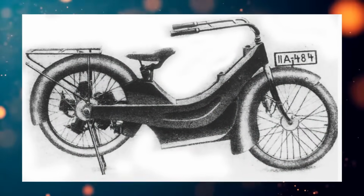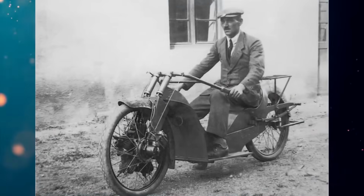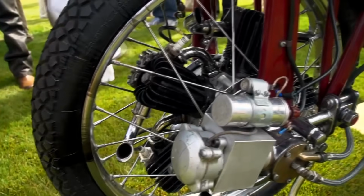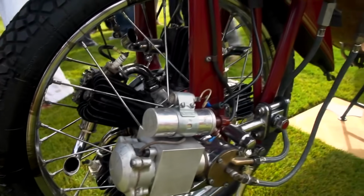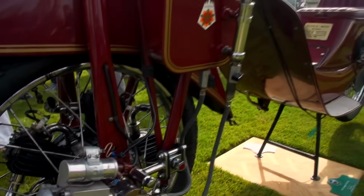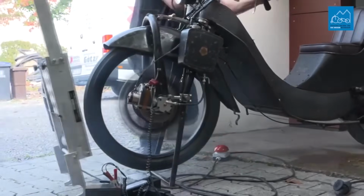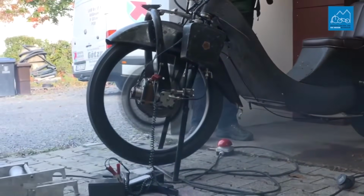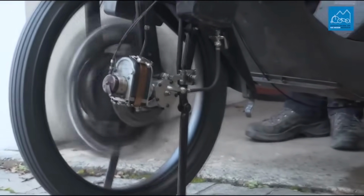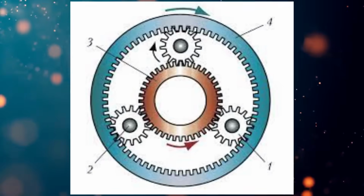During design and construction, several problems arose, leading the three creators to decide it was more practical to install the engine in the front wheel. The 640cc radial 5-cylinder engine was modified to increase its power, which reached 14 horsepower. A planetary gear was necessary for the engine because the calculated wheel's speed at maximum velocity was 600 revolutions per minute, while the engine produced maximum power at 3,600. We have a gear ratio of 1:6.